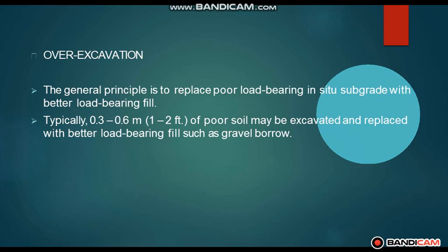Over-excavation. The general principle is to replace poor load-bearing in situ subgrade with better load-bearing fill, typically from 0.3 to 0.6 meters, that is from 1 to 2 feet.